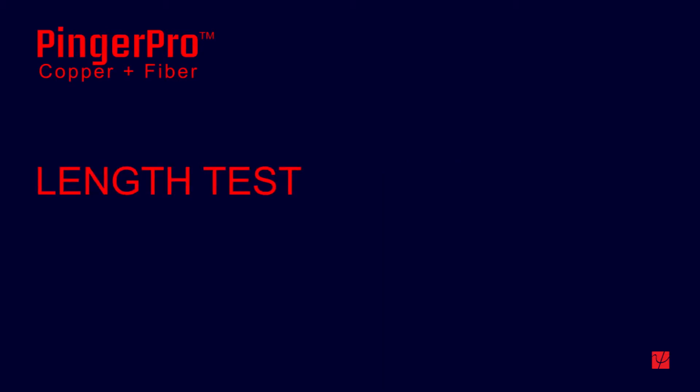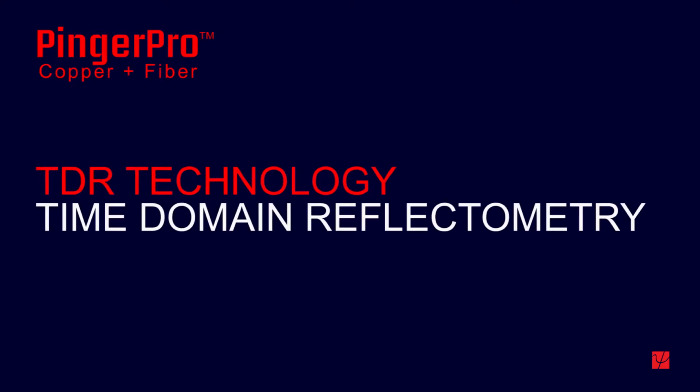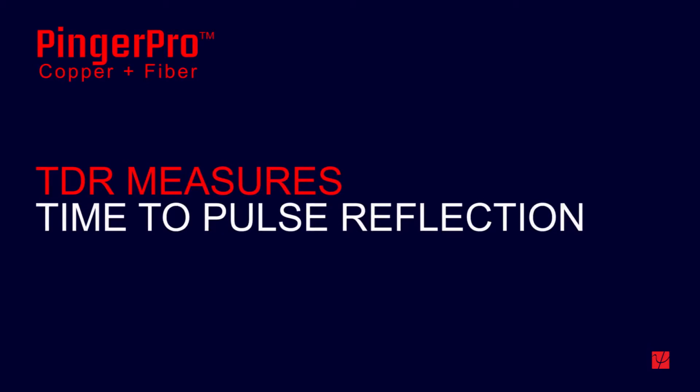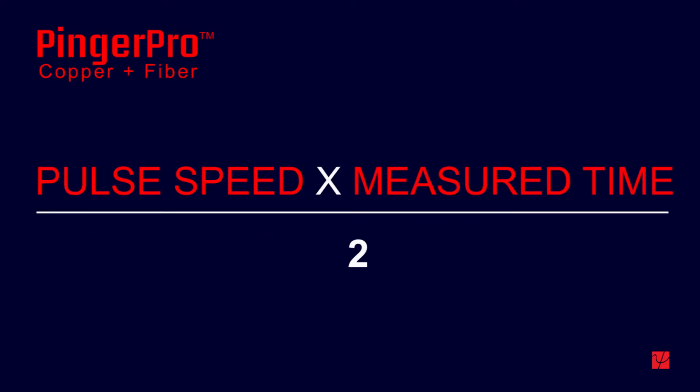The LENGTH test uses TDR technology, which stands for Time Domain Reflectometry. A TDR measures distance to a cable discontinuity by sending out an electrical pulse and measuring the time it takes to see the pulse reflection. Distance to the discontinuity is calculated by multiplying the speed of the pulse by the measured time and dividing by 2 because the pulse traveled out and back.